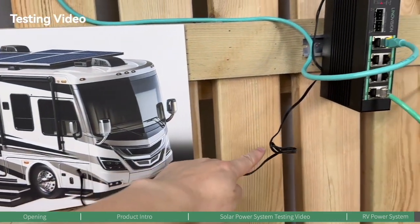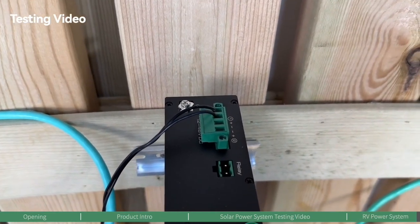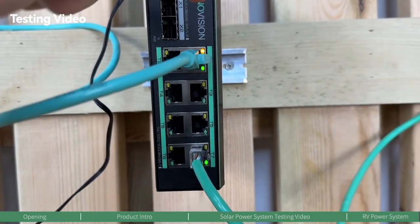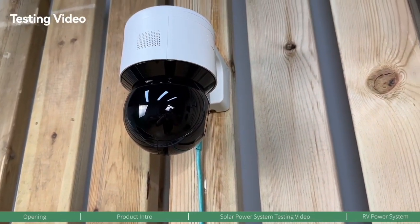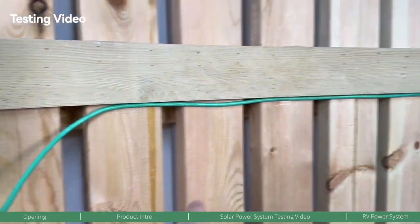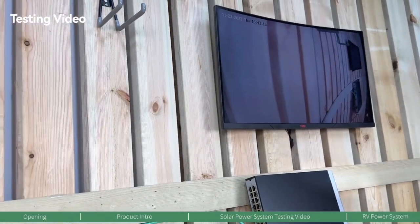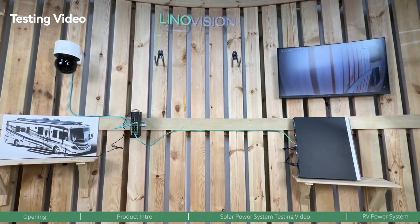It provides a centralized power management solution, crucial for environments like an RV where space is limited. It also simplifies the installation process, as only one cable is needed for both power and data, reducing clutter and the need for extensive wiring. By using a PoE switch, the RV's power system becomes more flexible and scalable, allowing for easy addition of new devices without additional power wiring.